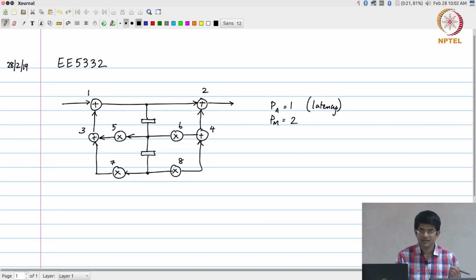And they are pipelined, meaning that on every clock cycle I could, if necessary, introduce a new operation onto each of those hardware modules. In the case of the adder, of course, it's fairly obvious because after all it finishes within one clock cycle, meaning that in the next clock cycle it is free to accept new inputs. In the case of the multiplier, it takes 2 cycles to produce the output, but the assumption is that it's anyway free to accept new inputs on the next second clock cycle, even though it is still working on the first set of data.